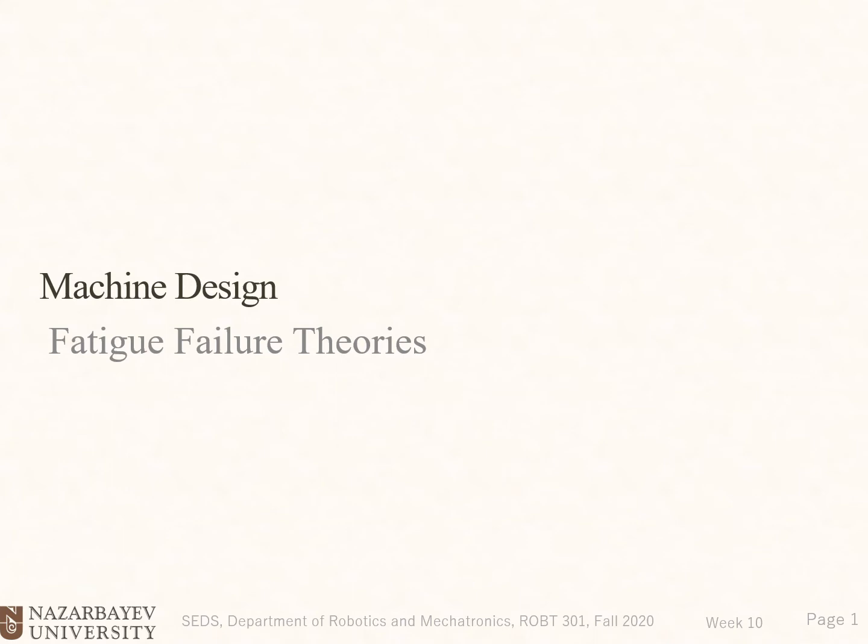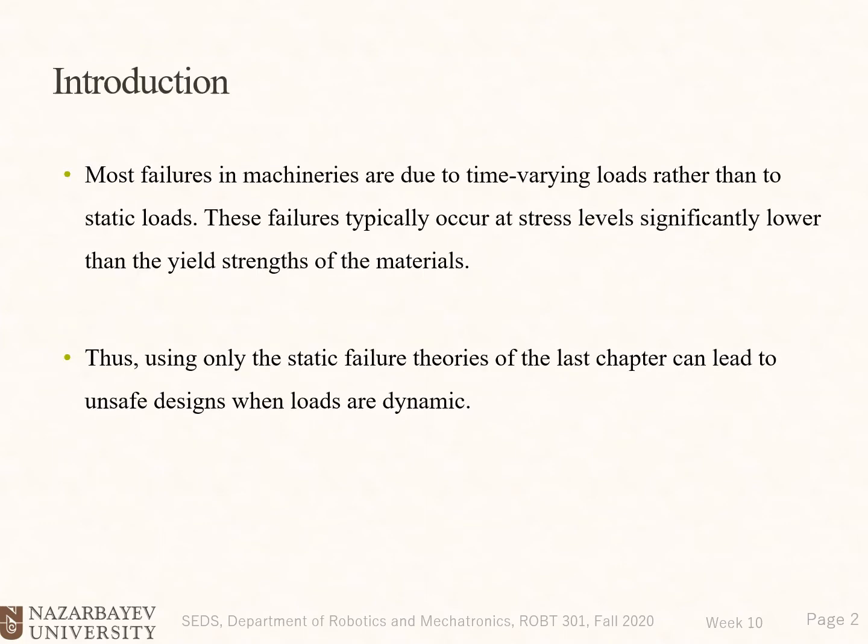In this video, we'll talk about fatigue failure theories. Introduction to fatigue failure theories. Most failures in machineries are due to time-varying loads rather than static loads. These failures typically occur at stress levels significantly lower than the yield strengths of the material. Thus, using only the static failure theories of the last chapter can lead to unsafe designs when loads are dynamic.